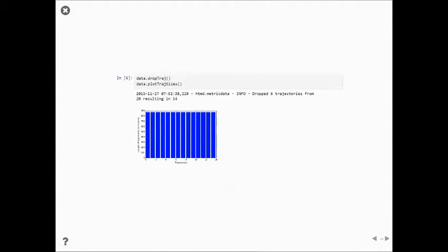Sorry, I wanted to mention something. In this command that you have, drop traj, this command up there, in your case it says multiple 350, right? So if you did the skip 10 at the beginning, change this 350 to 35, otherwise it will drop all of the trajectories. And you will not have any trajectories left for the analysis afterwards.